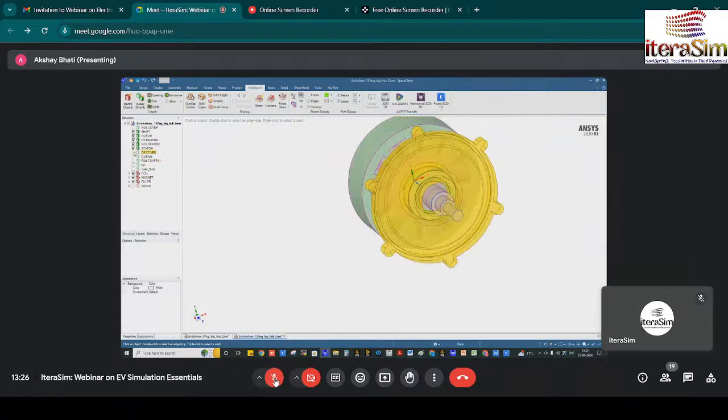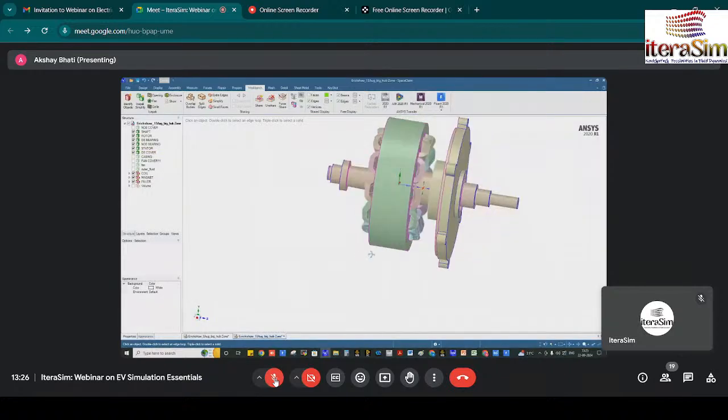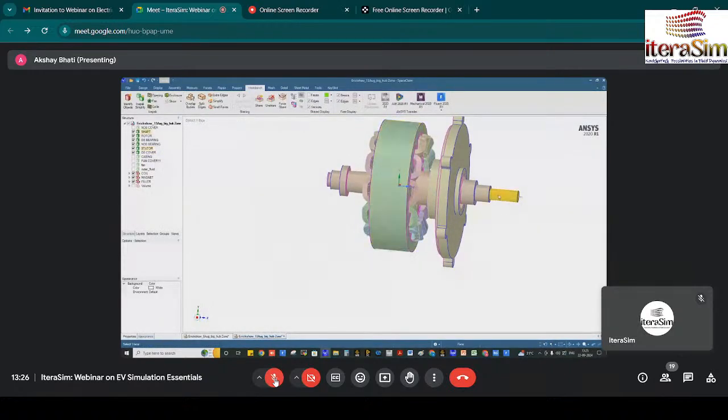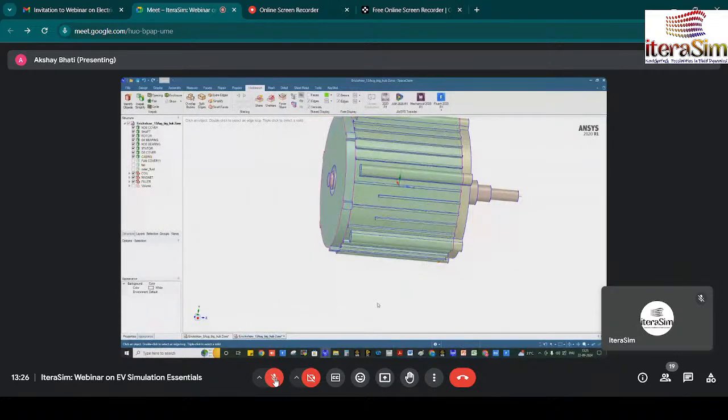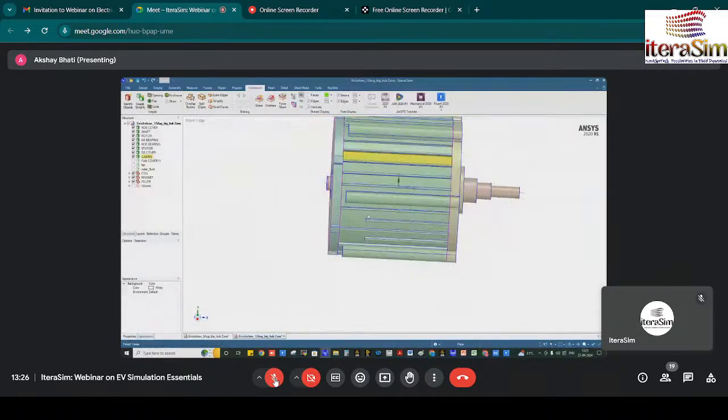After that, there is the cover, that is the drive end cover. After that, it will connect to the driving unit, and then we go to the ND bearing and the ND cover, the non-driving end cover. And that is the casing. Casing means here are the fins that are used to remove the heat. After that, there will be a fan.